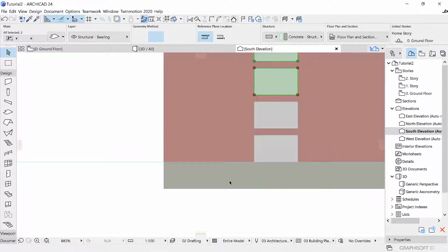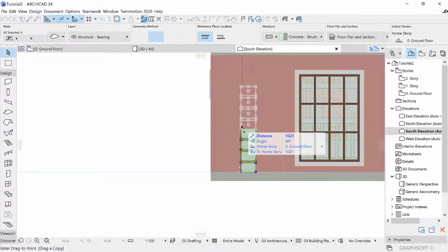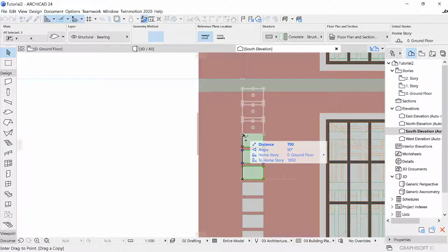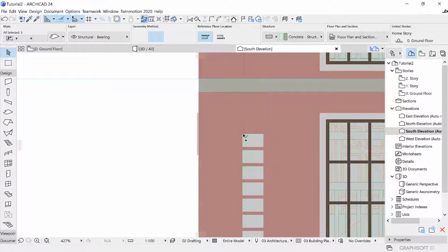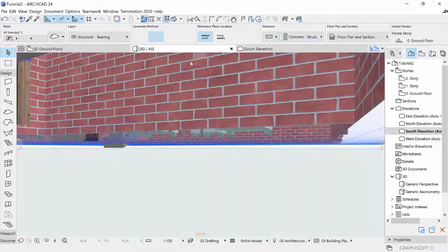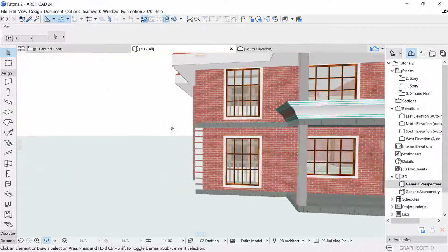Like I want to leave an interval of 50, 50, 50, so I can select all the four, and now I'm taking them to 1000. Should be okay. So of course you just repeat the same thing. I select the three and Control Shift D. I'm just dragging a copy to 750, and now I want to edit this one at the top. So I'm going to suspend the groups, and then I change its position like that, and that looks okay. So that's what we have so far.